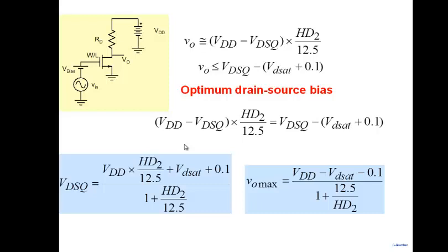When I'm looking at this amplifier, the swing at this first stage will be how much? See, the signal is traveling like this, going from here, here, here. Is output swing important here? Note that if all the amplifiers are running on 3.3 V, where are you likely to reach 3.3? Here. If it is 3 mV here, and this has a gain of 10, this becomes 0.3. And if this has a gain of again 10, this becomes 0.03. Swing is not an issue at all at the first stage.